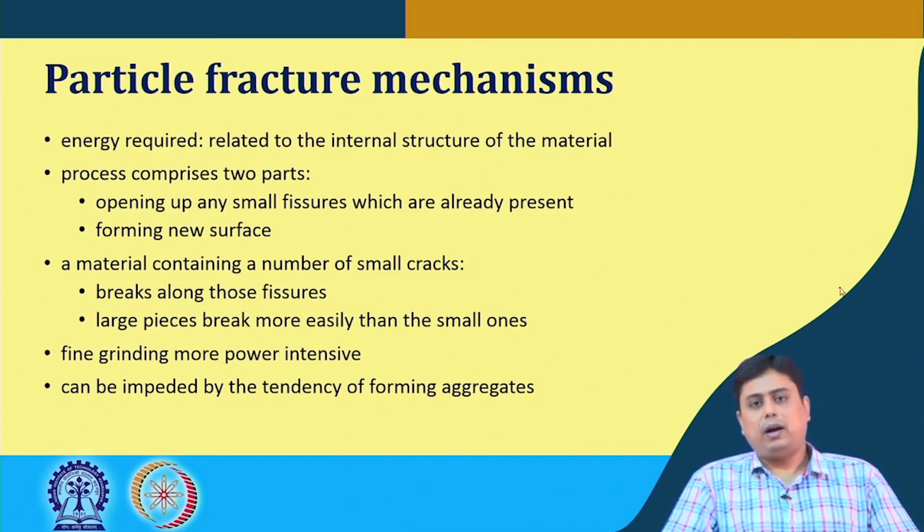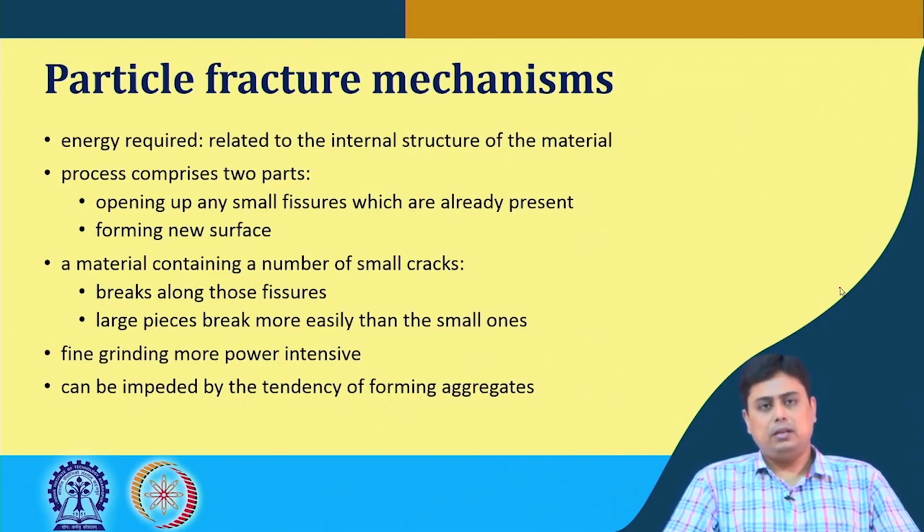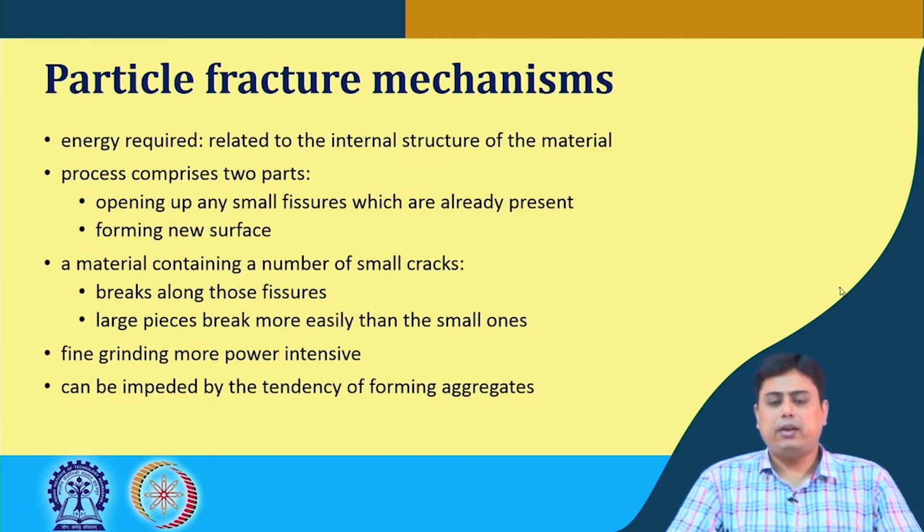Furthermore, when these small particles become sufficiently fine, their surface properties can change, and the whole process can be impeded by the tendency of these fine particles to form aggregates. So, these things have to be kept in mind. It is not just that I have this equipment and any material I can grind to a certain limit. That does not happen. We have to characterize the material before we put it into the appropriate grinder or crusher.